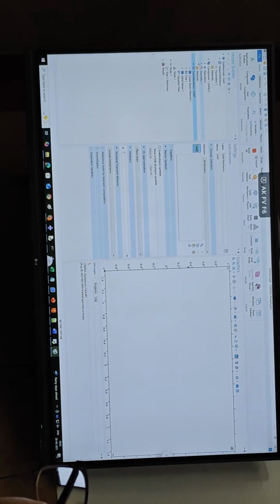Now for your problem in particular, we are going to first try to create a line to define the shape of your truss, and then orient beams along those lines. As I told you, the CAD interface here is not like a usual CAD interface where you can pull a line and draw. You'll have to define it by coordinates, and for a rectangle, you have to define it by rotations and also coordinates again.